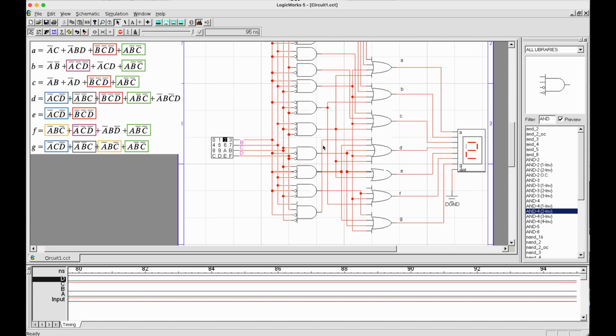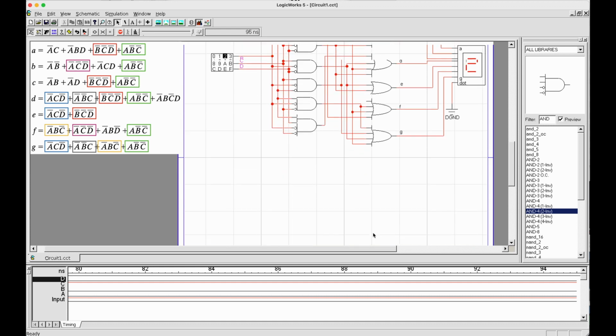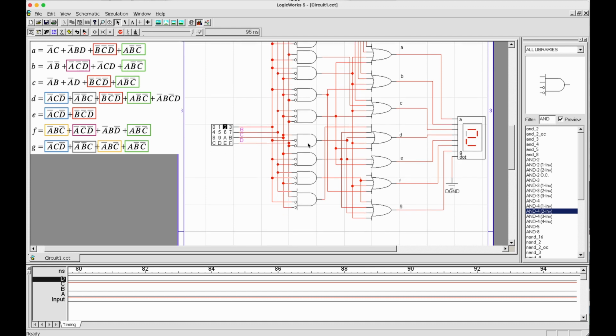Again, you can drag this wire across different places. Just make sure they don't form a solid dot. If they do form a solid dot, you will need to remove it and redo the connection again, which takes time. Or you can use Ctrl Z or Command Z, depending on whether your system is Windows or not. I map my keys, so I'm using Command.